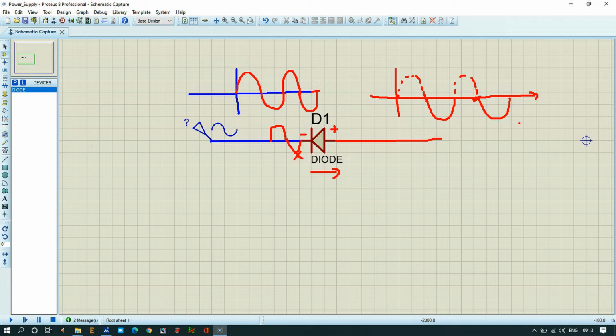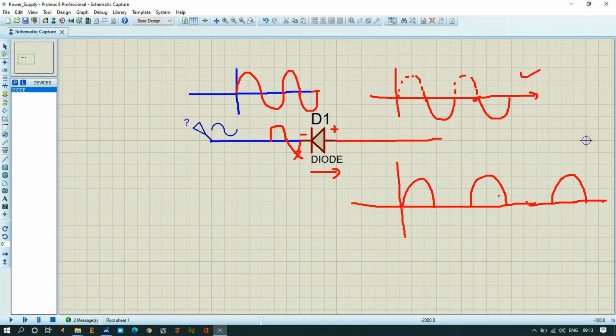Whenever we provide the input to the cathode terminal, this is how the output is, and whenever we give the input to the anode terminal, we only get the positive half cycles. We will arrange it in such a way that we get only positive half cycles with no delay. Here in this case we are getting a delay. You can see in this area we have some delays. There is no waveform because the negative waveform has been blocked by the diode. So we have to rectify this. We have to bring another half cycle here to avoid the delay between the signal transmission.